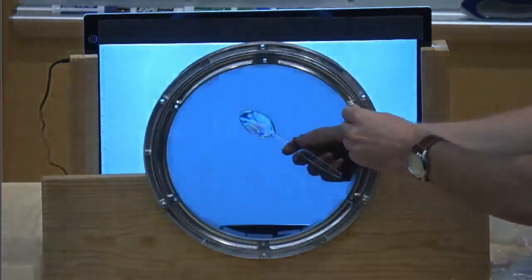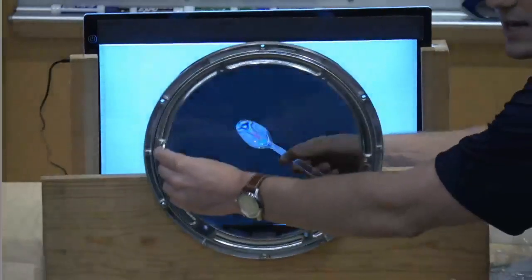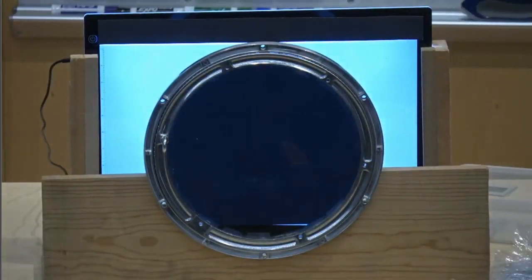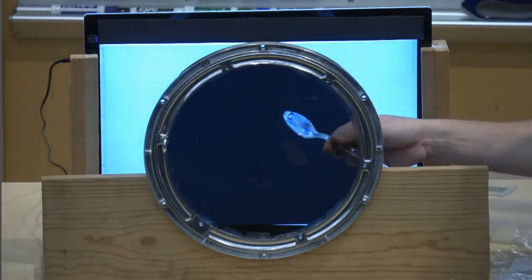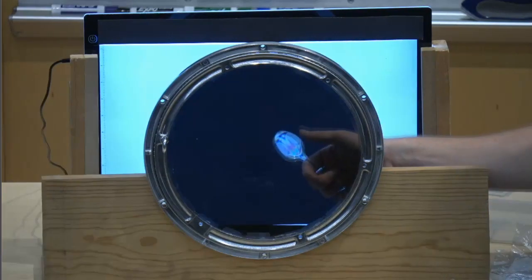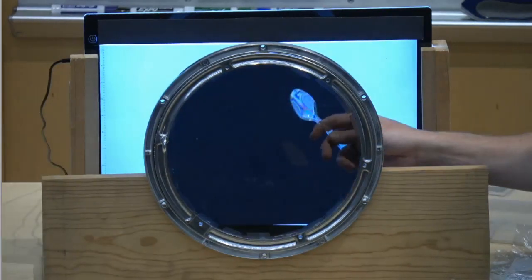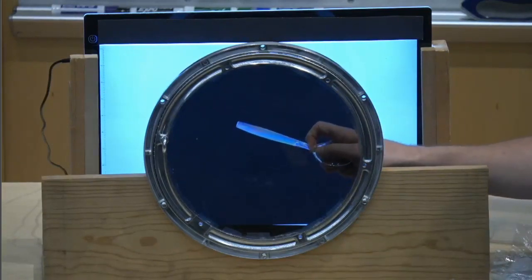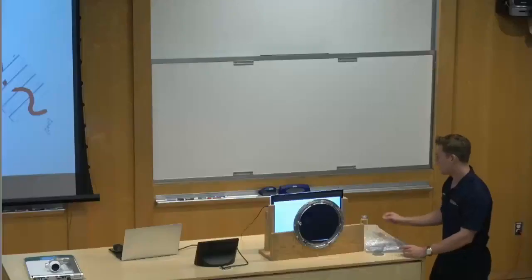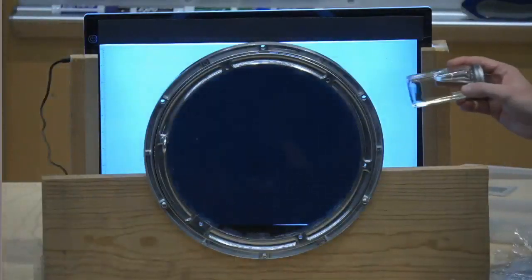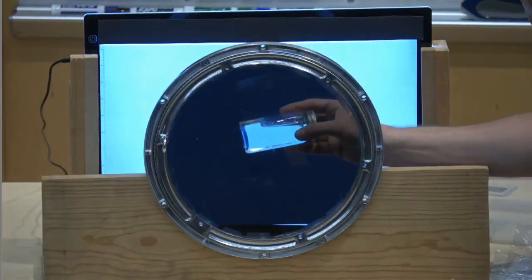This is used in manufacturing, where we can see the stress inside of the spoon. So if you were to cast this spoon into a mold, we can determine there's a high probability that it will fracture at the concave part rather than at the smooth part with very little birefringence.